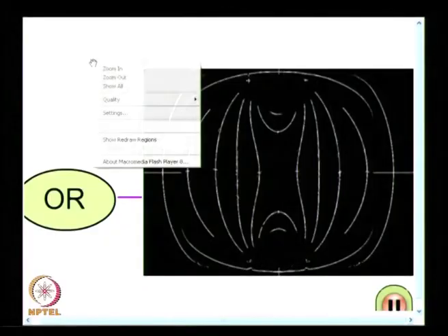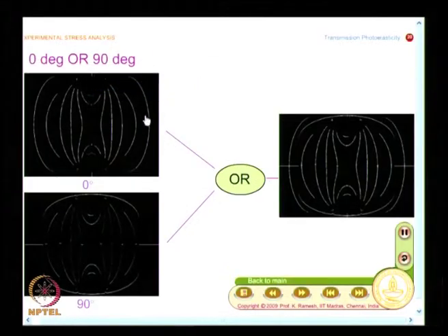If you go to another set of orthogonal scans, you are able to get all the fringe points, but noise in a different direction. So, when I do the logical AND, the noise is eliminated, that is the principle behind it. So, this is the OR operation of the 0 degree scan and 90 degree scan, and I have this fringe pattern.